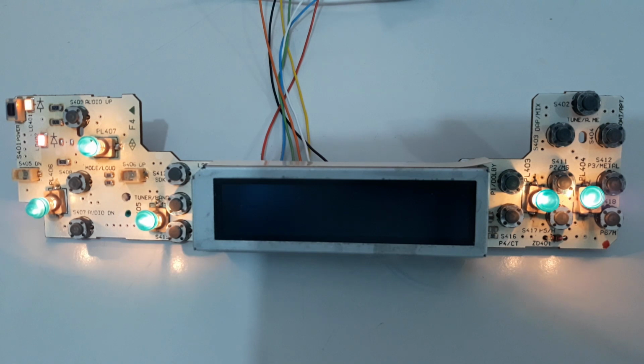As usual, we will find the same pins for connecting the panel. In this case, the data, clock, chip enable, and here we also have the INH, which is a value of VCC through R to keep it high. In the code, we have the same method for identifying the segments.